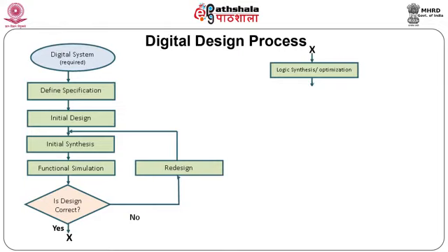Logic synthesis tools can be technology dependent or independent. If the synthesis tool is technology independent, then the optimization is independent of the resources available in the target chip. For technology mapping synthesis tools, the optimization is done using the logic resources available on chip.